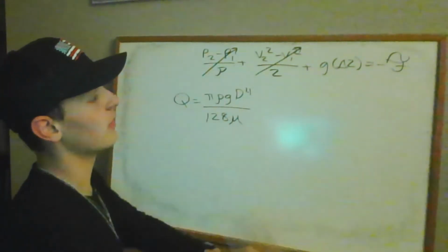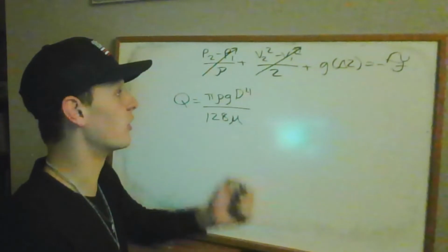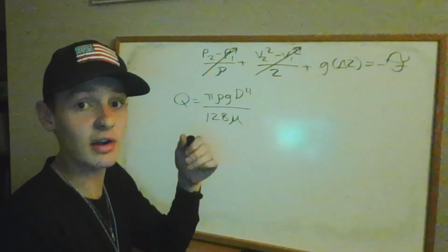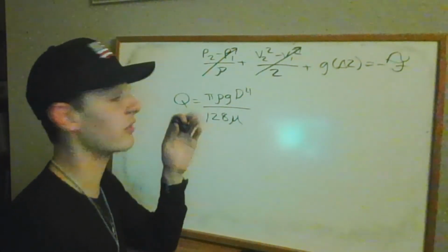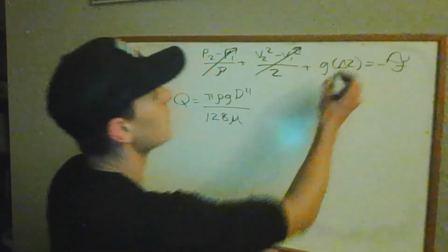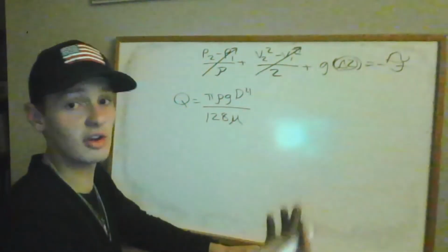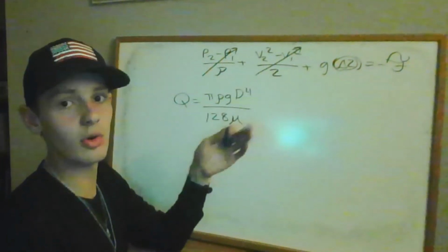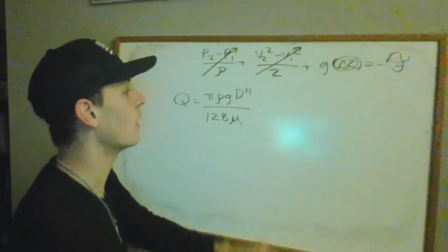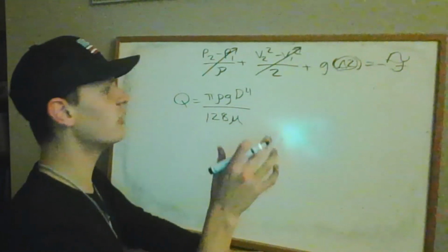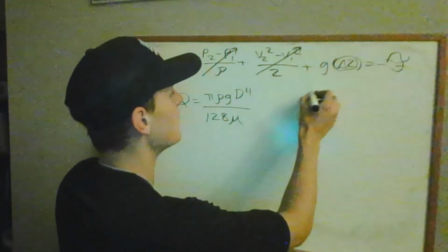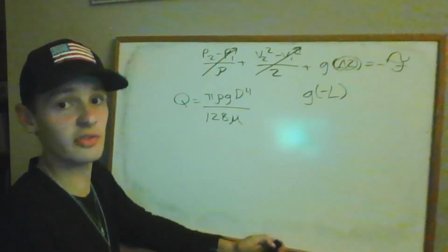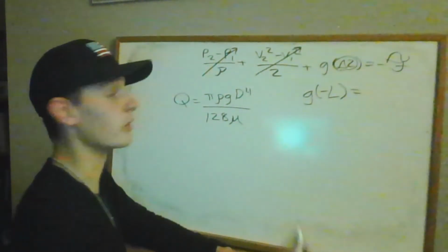And again, remember, the lack of change in pressure is due to the fact that we have our fluid in motion at steady state, and each end is exposed to the atmosphere. So you have the pressure force due to the atmosphere on both ends of our fluid. And then we have the change in altitude. We decrease potential energy, so this delta Z is actually negative, and it moves through the length, L. Because there's a decrease, this would be negative L, the opposite of the length, because the altitude is decreasing as the fluid moves down through the vertical pipe.